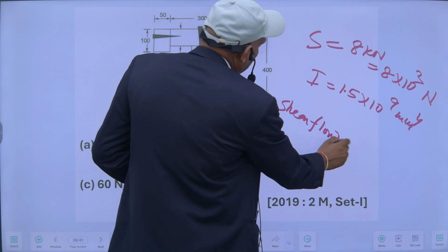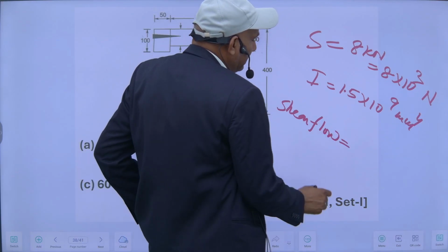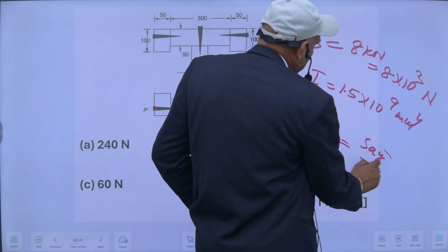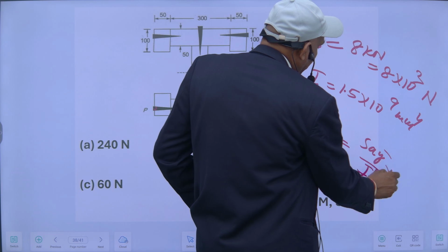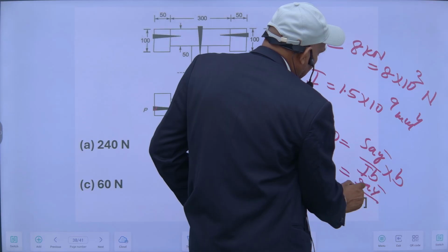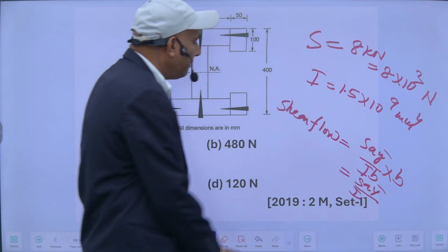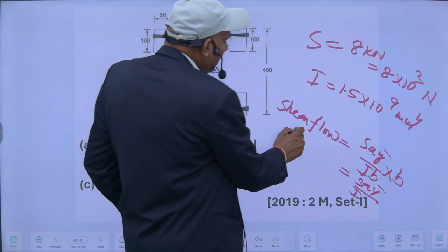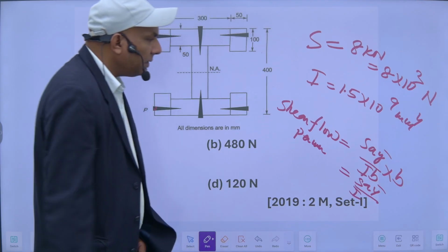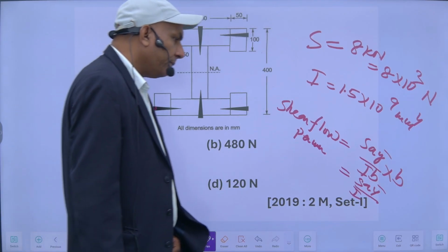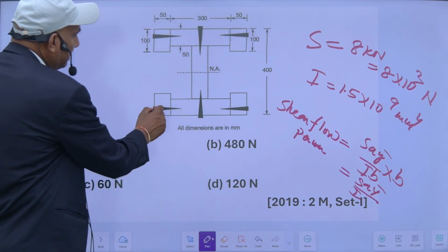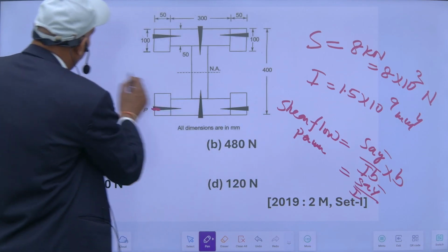means shear stress formula is this one. So when I multiply it by b, then it will be QAy bar upon I. So this will be the shear flow, means shear force per unit length, per mm length, Ay bar upon I. Now at this location, if I want to find, then shear force will be